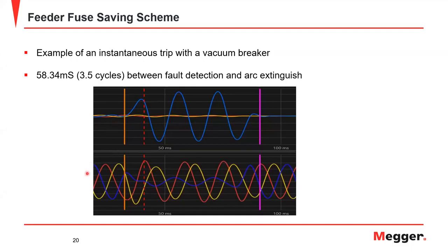You can also see good, healthy phase voltage down here. And then you have the fault strike. Voltage decays immediately. That's how you can usually tell the exact moment that the strike occurred. Current rises quickly as well. Throughout the fault, you can see voltage is maybe 30–40% of nominal on the faulted phase. The other two phases are a little bit affected, but they're almost normal.